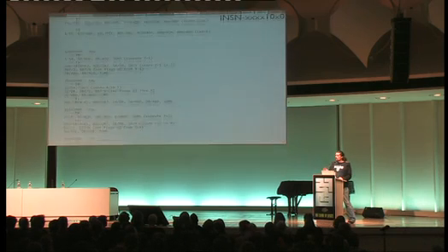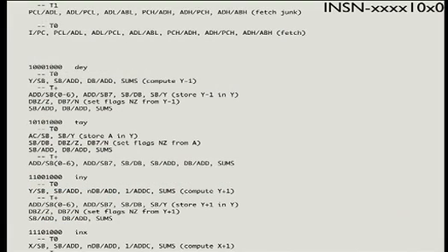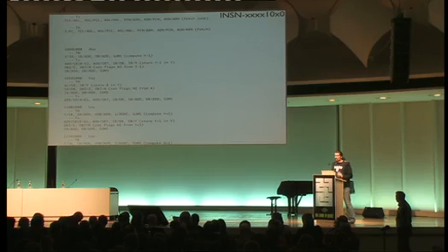One thing that we have, some really interesting internal representation, is the mapping from the opcode to what comes out of the random control logic as the very last step. So you can rather easily look up what's going on the bus in every cycle of certain instructions. But we're not only investigating the 6502 by itself, but also the different 6502s that are out there. There are so many things to do.